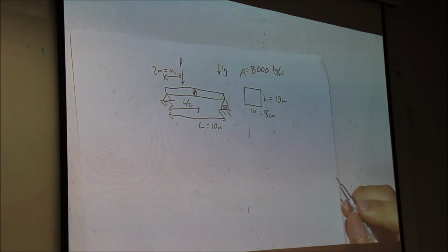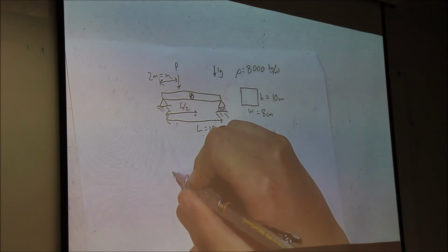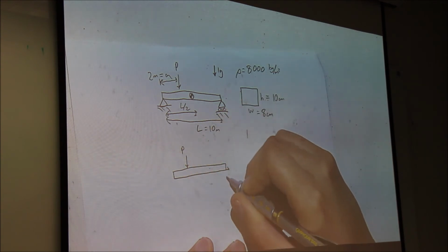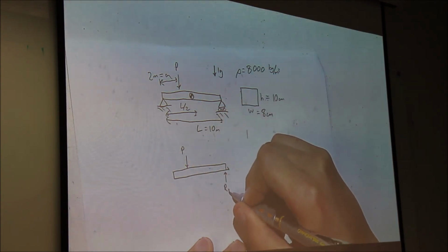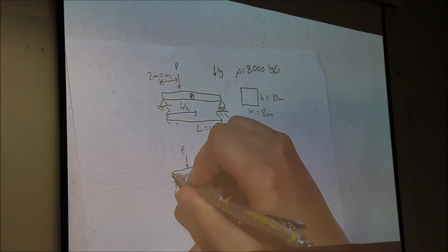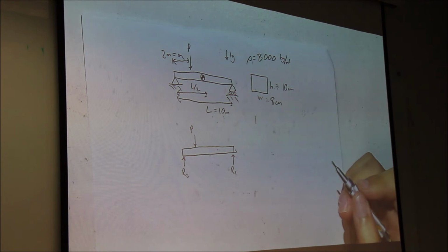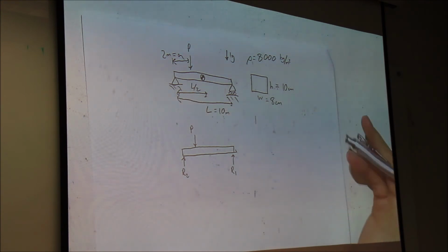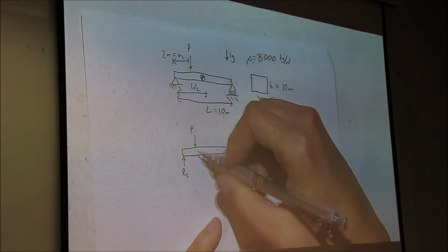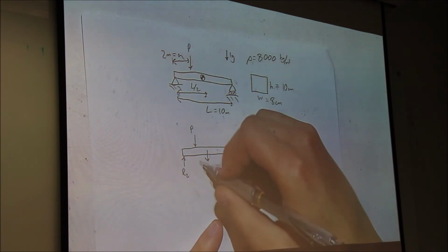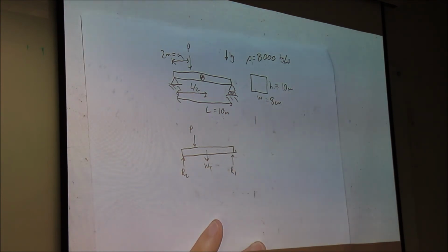Okay, cool. So first thing we should do, let's draw a free body diagram of our beam. So we know we have a force P acting here. We know from before we have R1, R2. I'm going to ignore R3 because we already showed it's irrelevant. There's one more force though. Where would that be? Center of mass, very good. So we'll show him being pulled down by some weight total, okay?